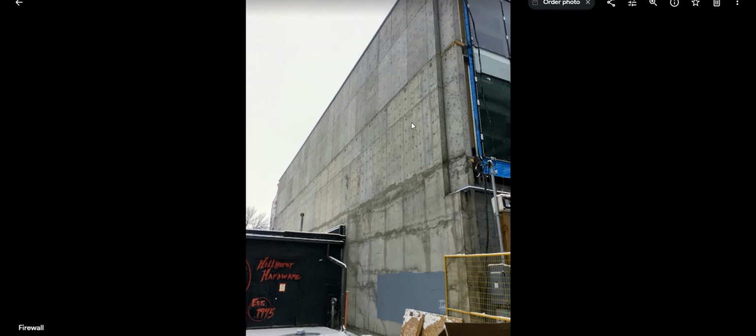And so quality-wise, I would say, because you're leaving this exposed, the poured concrete, in my mind, is a far better option for this. I'll call it firewall on the property line, and only because I think over time it would just weather better, basically. So concrete block is a little bit more porous, and it has mortar joints between the blocks. So things could break down over time, whereas the poured concrete is going to stay pretty solid. So I'm sure this is more costly to go the poured concrete route, but I would say it's a better option if one's being forced into this situation.